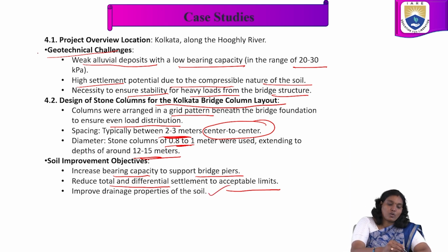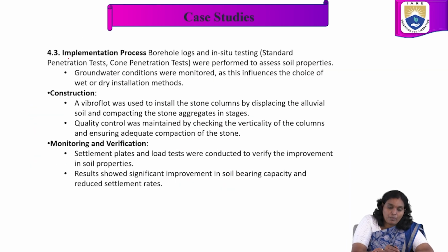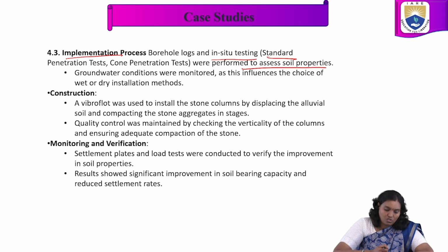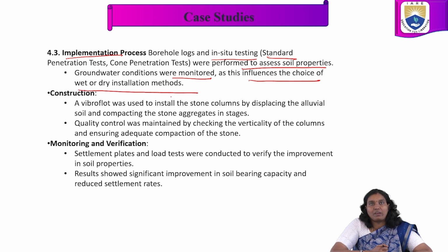These are the project overview, and also the implementation process. So borehole logs and in situ testing, where the standard penetration test and cone penetration test were performed to assess the soil properties. So these ground conditions were monitored as this influences the choice of the wet or dry installation methods.